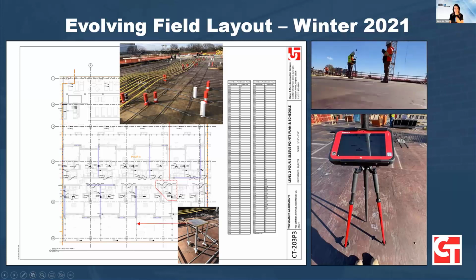Sorry, I didn't mean to interrupt. No problem. One other thing I wanted to add, one of the advantages to this Hilti system that we have used some, you can actually load a CAD file directly into it, completely independent of that point layout add-in for Revit, and work straight from the CAD file to generate layout points. And it's more or less all self-contained right there on site.